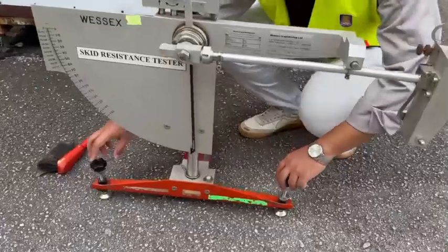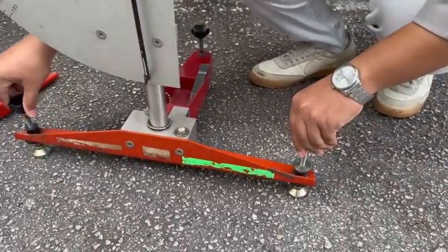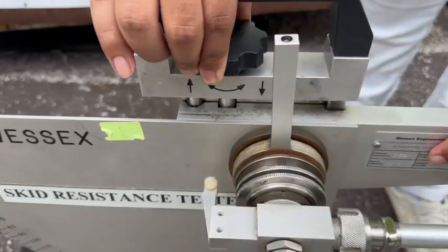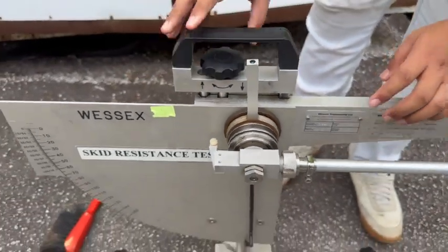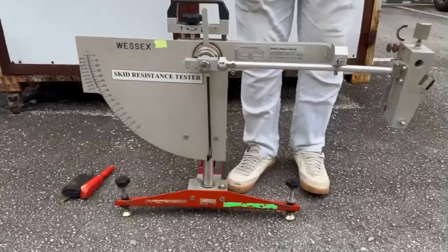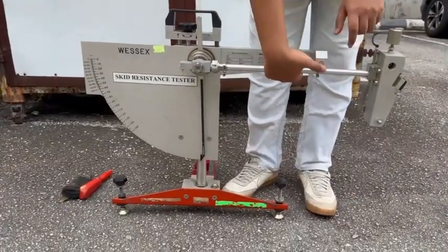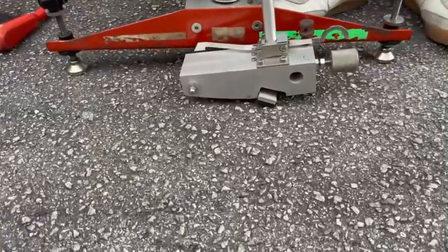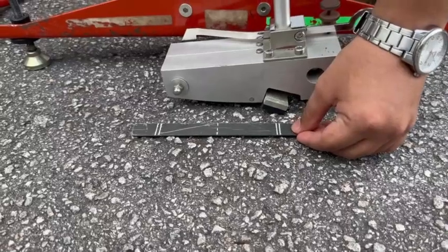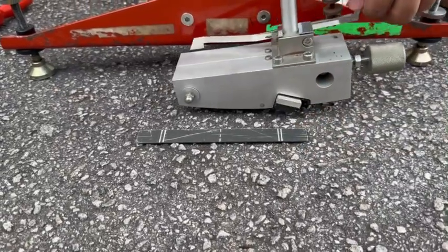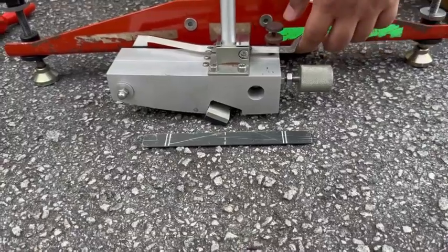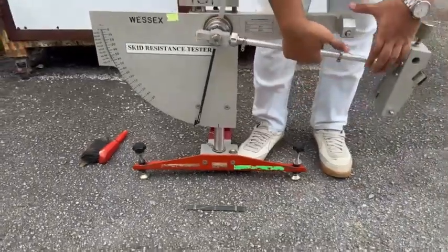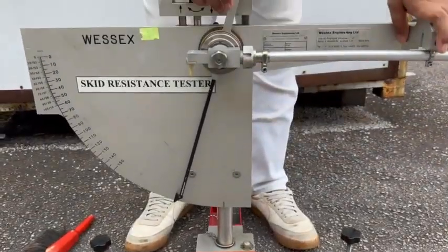In this test, first, stabilize the apparatus by adjusting the leveling knob until the bubble in the spirit level is centered. After that, to ensure the pendulum arm is in the correct position, adjust the height of the pendulum arm by turning the lifting screw and the knob behind the scale to obtain the optimum position, which makes sure the rubber is in contact with the surface when the pendulum arm swings. Ensure that the contact between the rubber slider and the surface before and after the swing is within the acceptable range.